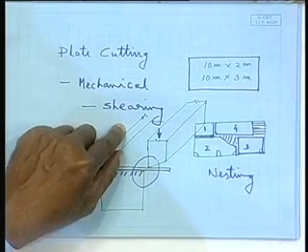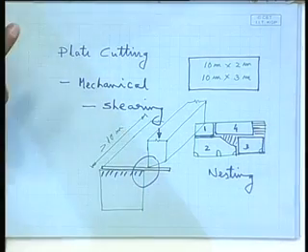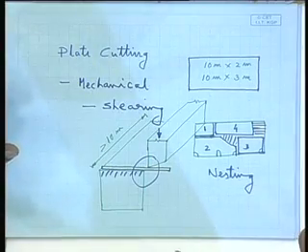But what is happening is that the edge is work hardened, and now that edge will get fully fused, because all these cut edges invariably will be welded to something. None of these cut edges will remain free, there will be some free, like the lightening hole in a floor, I am cutting it. Those edges are free, let them be free, and they are not subjected to heavy stress levels. And whatever work hardening is taking place because of such cutting is also not of that level that it can cause any eventual loss of ductility such that a crack will form. Those chances are very less, because of the location where it is happening.